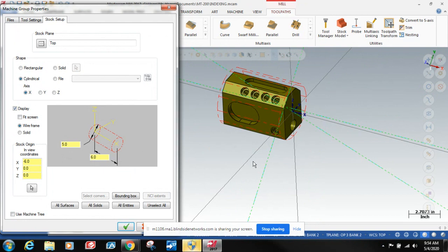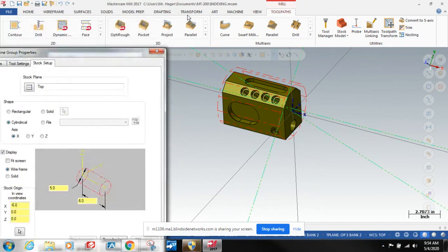Just spitballing here. So how do we change the origin of the part? You have your part there at 0, 0, everything in the middle, but my X and Y, the origin. Ordinarily, when you import the model, that's where it's going to land. That's what I thought too. But if it did not, you can use the transform functions to move it around. And then drag it down, right? Yeah, so I would get it positioned there on that origin, first, before you start any of the other operations.